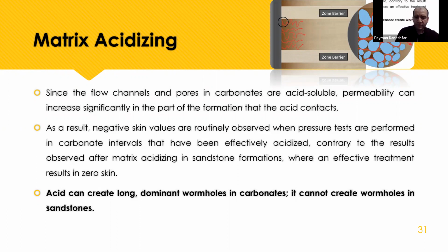But in sandstone formations, after matrix acidizing, we get an effective treatment result, but our skin is 0. So acid can create dominant wormholes in carbonate, but it cannot create wormholes in a sandstone. It just dissolves some soluble elements that plug the pore space.